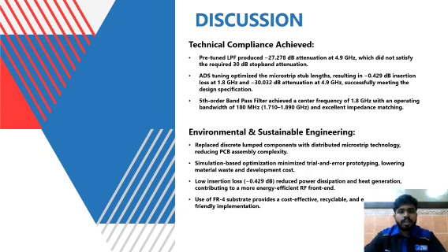The ADS tuning improved the low-pass filter attenuation from negative 27.278 dB to negative 30.032 dB while maintaining a low insertion loss of negative 0.429 dB. Richards' transformation and Kuroda's identity enabled the practical implementation of the distributed filter. In addition, using distributed microstrip technology reduced PCB complexity, minimized material waste, lowered power consumption, and supported environmentally sustainable engineering.